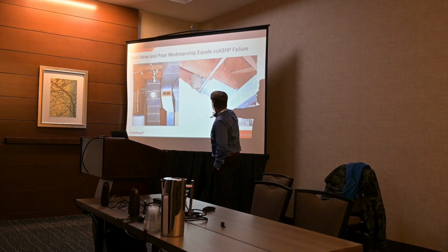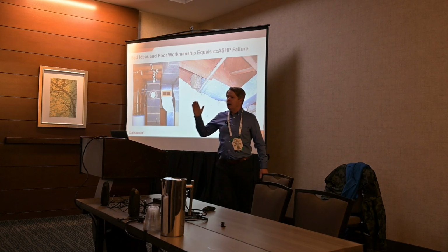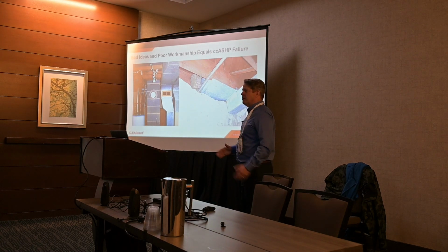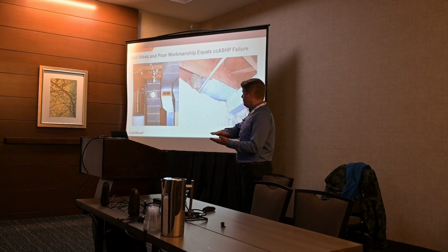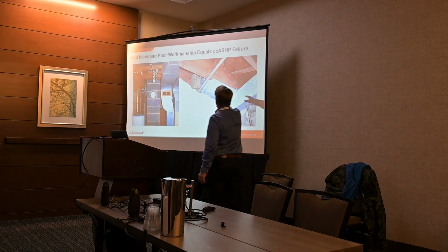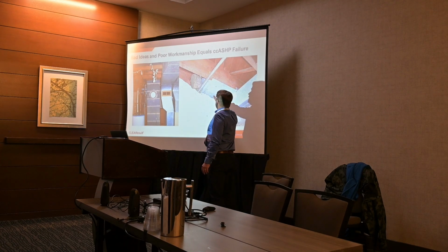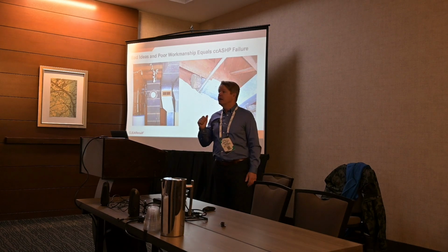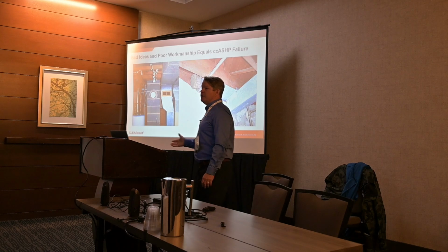This panning is right up against, it's not resolving really great on the screen, this is a rubble foundation in an old home, and this panning is right up against where the shoe plate is sitting on the rock. Now, this is typically a tight space, right? Rock's nice and level, there's no leaks there, right? It leaks like all heck. So when this is running and it's really cold out, where is it getting a lot of its return air? Outside, right? It's 20 degrees outside.